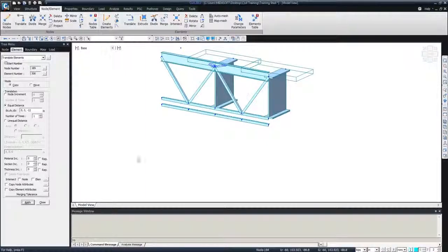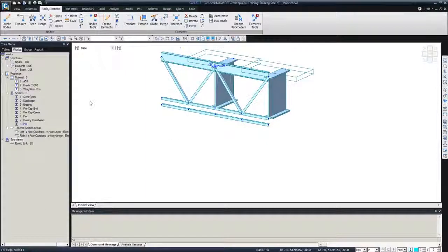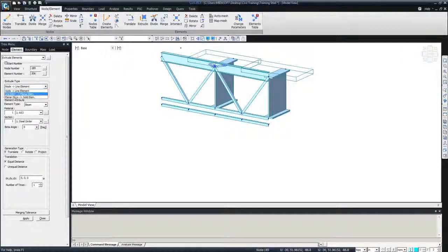I'm not going to use this as a structural element. So you see how it works. Again, going to extrude, and under extrude select line to planar elements, and you see here the source, you have the option to remove that. So I definitely keep this on, and after the abutment is created, this beam will be removed, sorry.